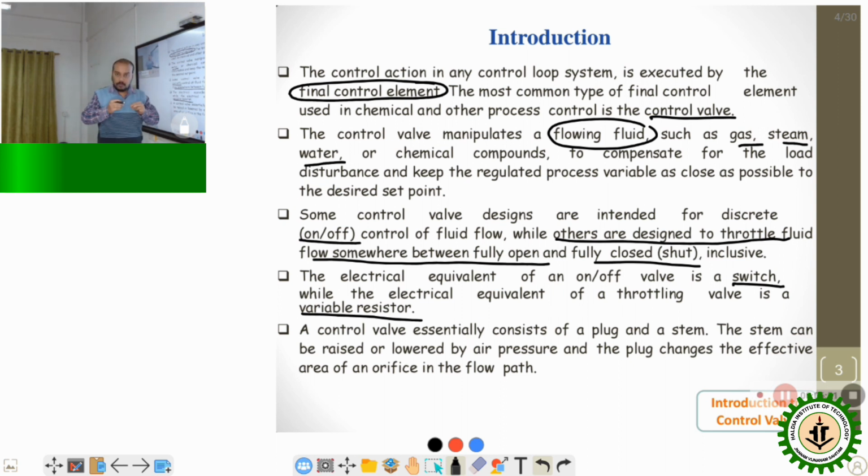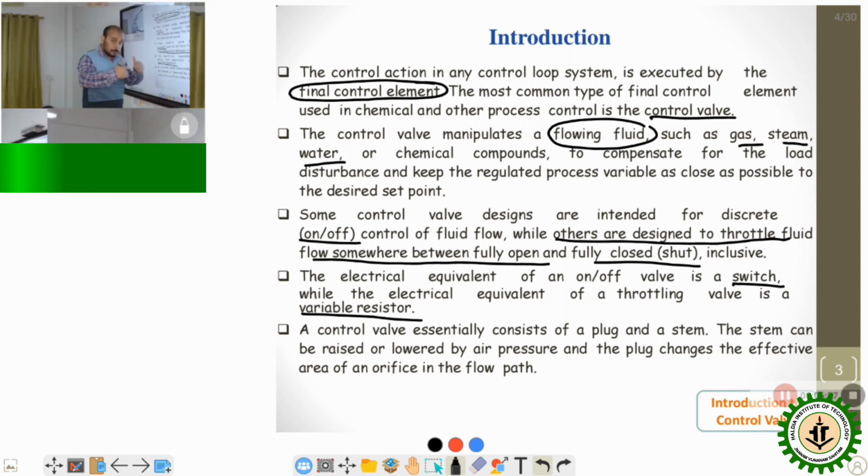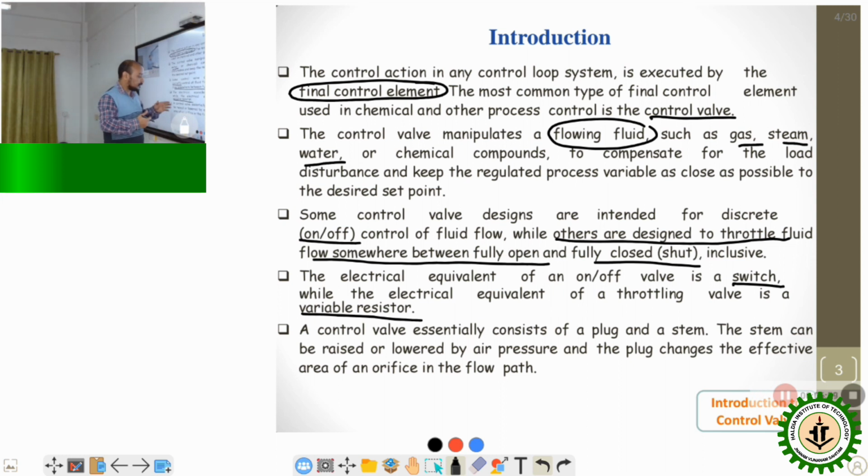If you put it out, there will be no resistance; if you put it back in, you get the same resistance. But if we talk about proportional changing of the control valve opening, then you have a variable resistor, in which we are able to change the opening of the control valve. Here we are changing the value of the resistance.